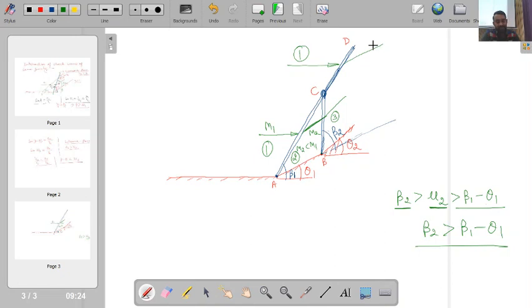Okay, so ultimately you can see over here that this flow, which is upstream of ACD, has the same conditions, equivalent to that of Mach number 1. Now below point C, first this flow deflects through the wave AC, becoming Mach number M2, then it deflects through wave BC, and then it becomes Mach number M3. Whereas for this particular wave CD, it is only passing through a single wave. So this is very clear to us that an oblique shock wave results in change in entropy of the fluid medium.